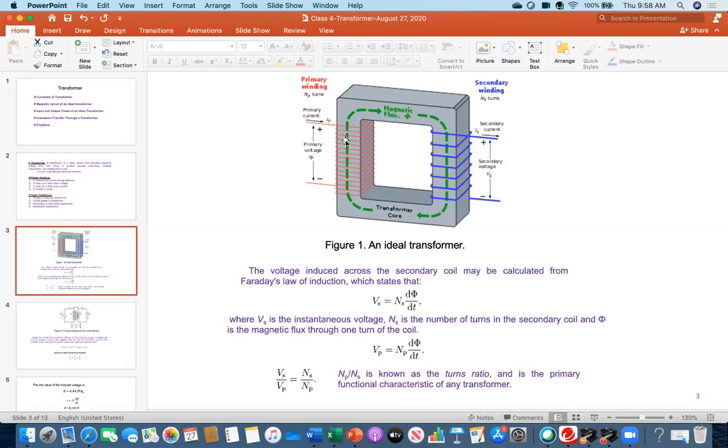And then can you see that green colored thing? Magnetic flux. Because you applied the voltage, consequently there is another induced voltage on these coils according to Faraday's law of electromagnetic induction. Voltage will build up, consequently there will be current, and that current will cause flux, which is that magnetic flux. And the characteristic of the flux, because this is a magnetic material, is that it will start flowing through the magnetic material.